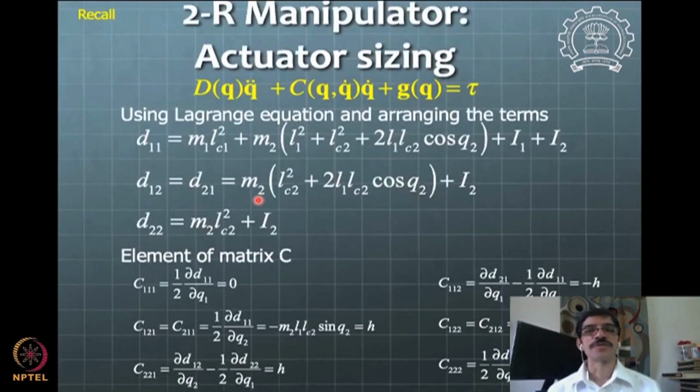And when you come to actuator sizing, we need to go back to the modeling part to some extent. You remember the model that we derived for our manipulator. From this plan of Q1 and Q2 trajectories, one can get Q double dot and Q dot, all these things as desired values, and then I can directly get the torque which is required to achieve that.